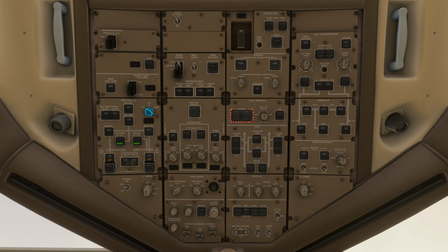If you want the airplane auxiliary power unit, you just need to take this switch to start and release it to on, and make sure APU generator is on. Note, in all normal operation of the Boeing 777, APU generator always stays in the on position. You only turn APU generator off in case of maintenance and non-normals. So, if you have the right procedure, APU generator should be on already, and then you start your APU.